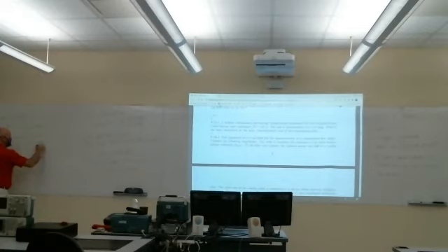But in this case, both those tangent beta L terms are 0, and we're left with Z0 over Z0 here, and just ZL here. So the input impedance at this distance is equal to the load impedance, 72 plus J 42 ohms.